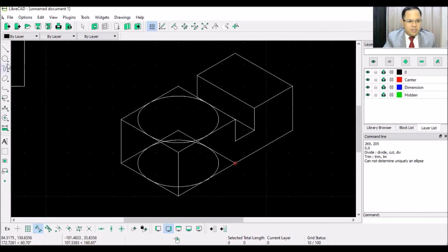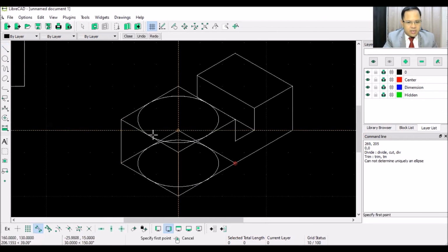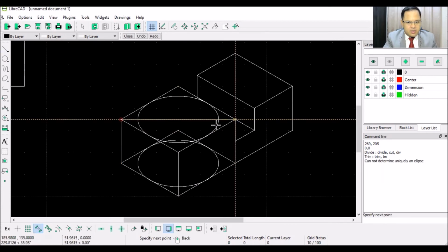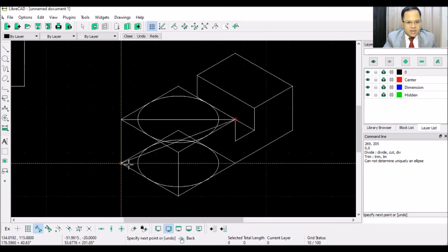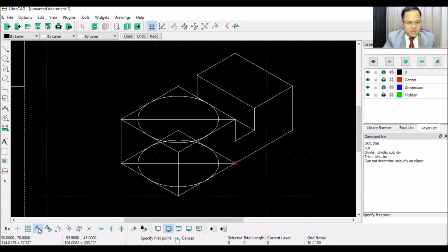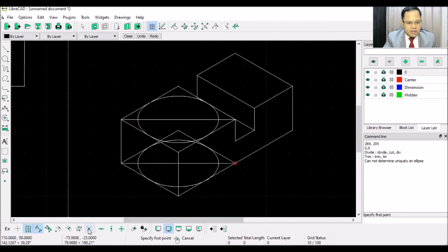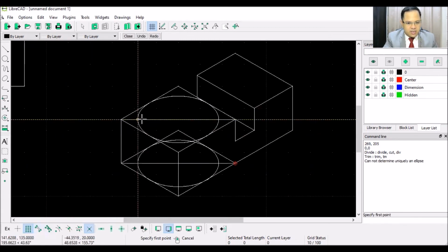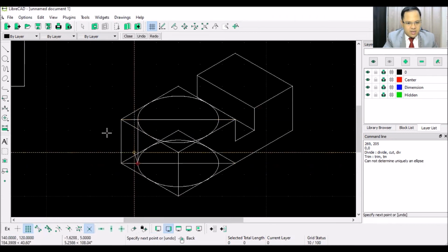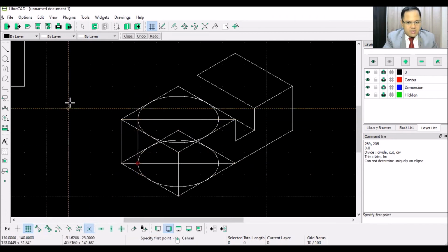Then this time, I want you to click on this line, then 2 points. I want you to select the 2 lines there, 2 lines there also. And change the 2 points here in grid, I mean intersection. Deselect snap on endpoints. So that's it.